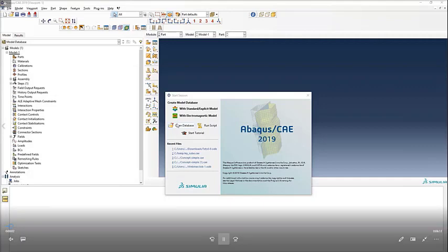We just finished talking about customization within Abaqus CAE, and now we're going to get into two different demos: a kernel script demo and also a GUI demo for an Abaqus CAE plugin. For both demos, the Python API, application programming interface, for Abaqus is used to interface with CAE. For the kernel demo, the Abaqus scripting interface, or ASI, is used to help create the Python script that will be used to build the entire finite element model.